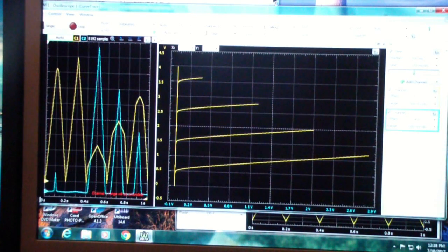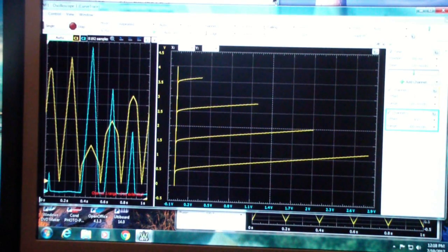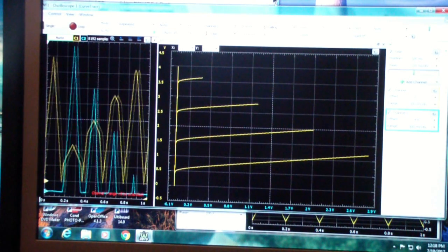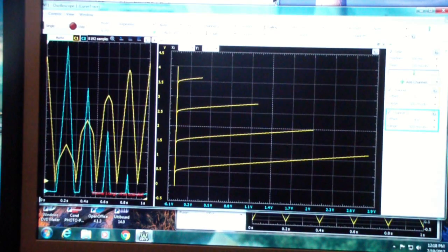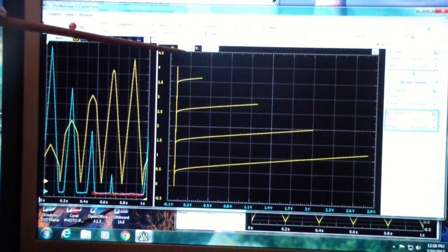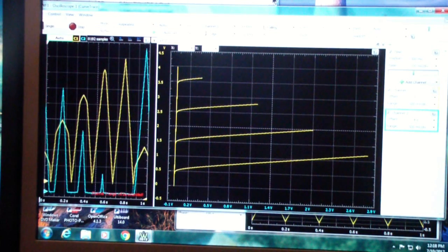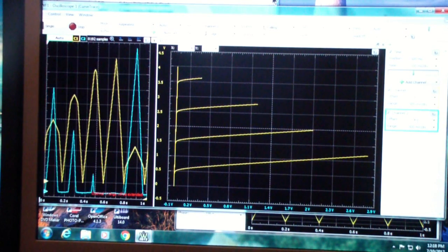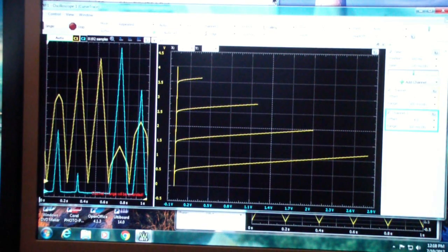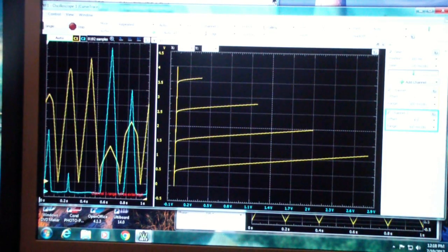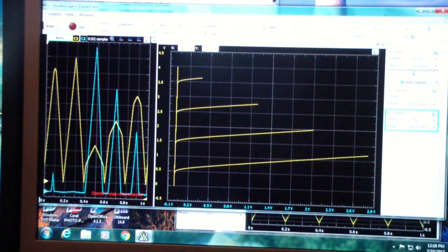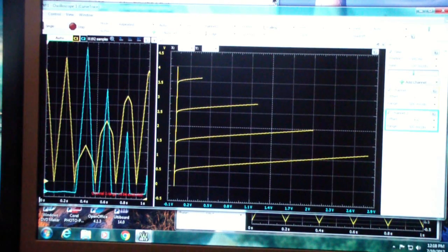And once again, I'm not doing that to encourage people to try to produce commercial curve tracers with the Analog Discovery. Instead, what this video is going to be about is the features of the Analog Discovery that allow you to do really neat things like this. Now, I will point out that there is no additional hardware. Let me repeat that. This is done entirely with the Analog Discovery and the WaveForms software that comes with it. The only external device is the 3906 transistor that we're doing the traces on.